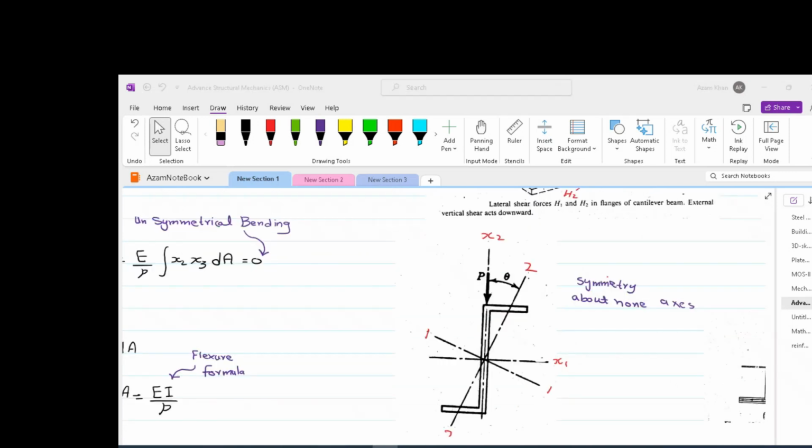We are now in a better position to discuss unsymmetrical bending. Unsymmetrical bending is defined as the bending caused by loads that are inclined to the principal planes of bending. The example of unsymmetrical bending is, as we discussed, the roof purlins that, because of the inclination of the roof, are subjected to loads whose planes make large angles with the principal axis of inertia of the section.